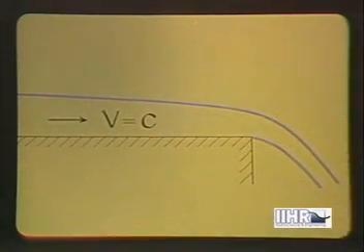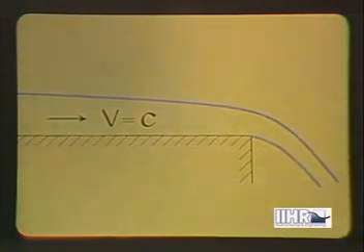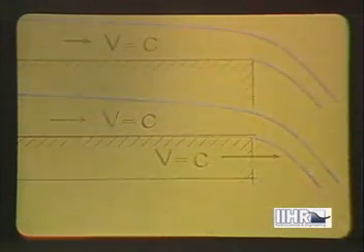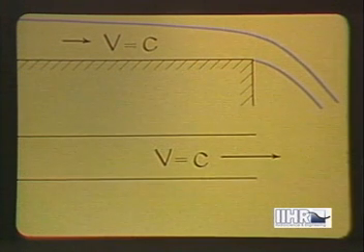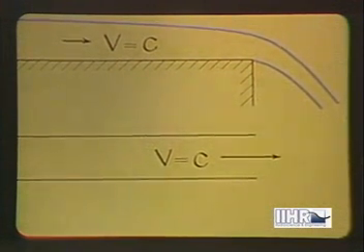Such flow is closely analogous to the flow of water in a long channel that ends in an abrupt overfall. As the depth of the flow decreases with distance downstream, the velocity increases and the Reynolds number remains constant. The limiting depth of the water is that corresponding to critical flow near the brink. Similarly, the limiting density of the gas at the outlet will be that corresponding to the velocity of sound at atmospheric temperature.